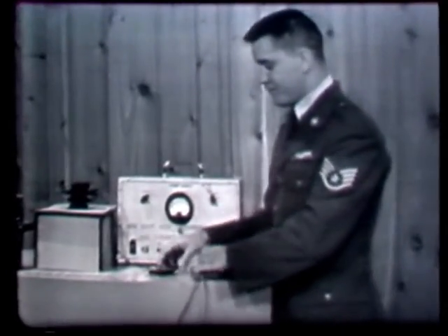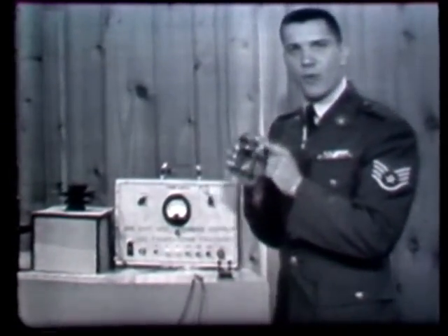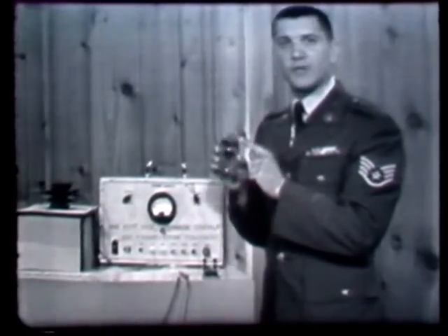Thus, we can conclude that some of the windings or turns of this 300 turns winding must be shorted. Well, as a matter of fact, I've already figured it out, and approximately 70 turns of this 300 turn winding are indeed shorted. Now we see then that for a shorted transformer winding, the ohm meter will indicate a resistance less than the normal resistance of the winding. Now, of course, the greater the number of turns shorted, the greater the decrease in the resistance of the winding.